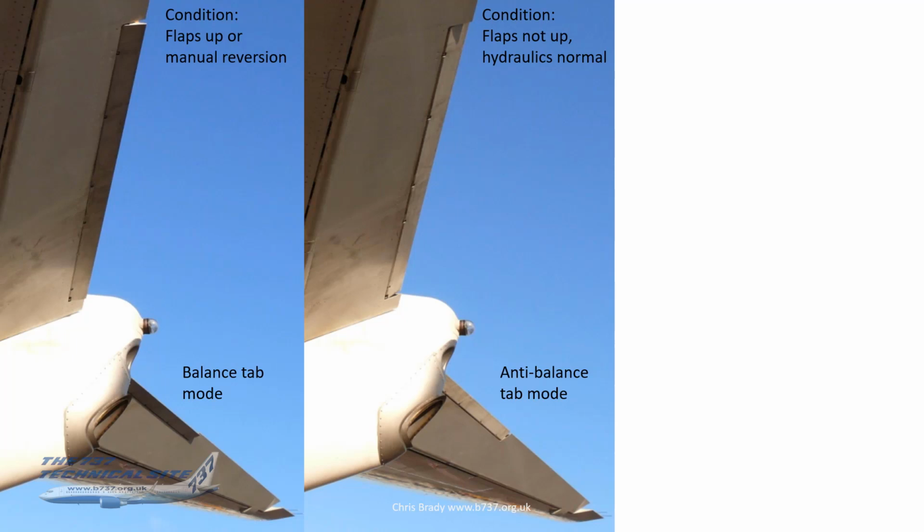I then got the FO to extend the flap just to 1, and what happened was the tabs reversed position, as you can see here. So this again is hydraulics on. The only difference between the two photographs is that in this second photograph, some flap was extended.